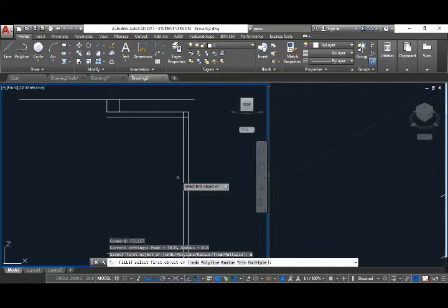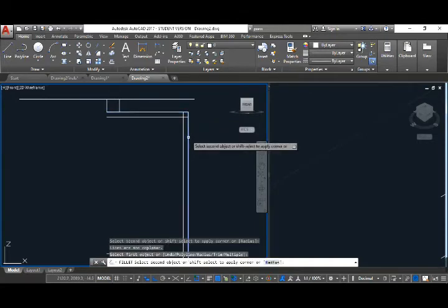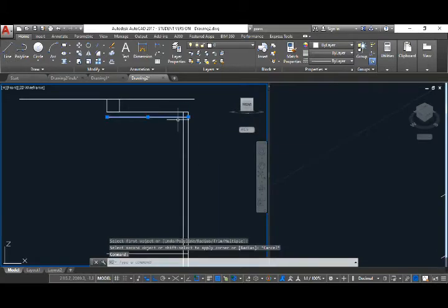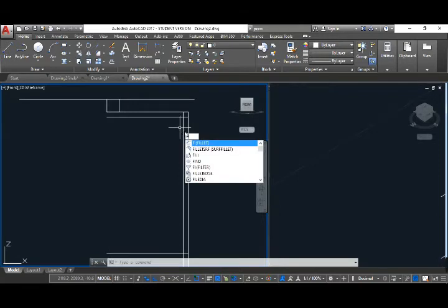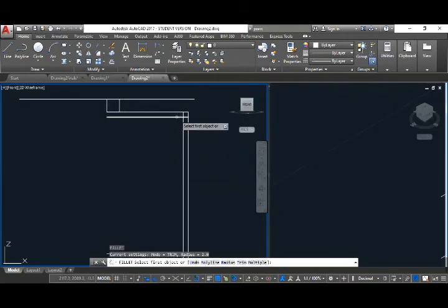Now, after making the interior walls, we're going to fillet all the corners to make sure that all the corners are smooth once we revolve this cross section. So we're going to set the radius to 2 cm, and we're now going to fillet the upper inner wall.